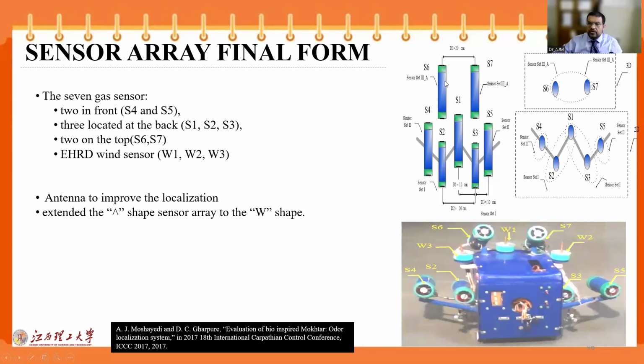Two more sensors I put at a height of 20 or 30 centimeters from my robots at the top, as you will see here. This one is for when I have the distance to my plume, as I showed you in the formula based on the Gaussian process; this odor will take height. These can increase the chance of detection. Then, as you remember, I told you that with the help of the direction of the wind, we can better detect the direction of the odor.